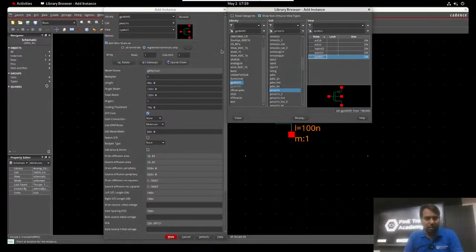Okay, that is NMOS. We have a lot of NMOS options. NMOS 1 volt, which is a 3 terminal device, and HVT, which is high threshold. High threshold means that in terms of layers there will be a difference: the oxide becomes thick if you are taking the layout. Okay, in terms of HVT, as a circuit designer, you will find a higher threshold voltage. It is more stable. It will have more power dissipation, but the speed is high. Okay, so you can take NMOS 1 volt.